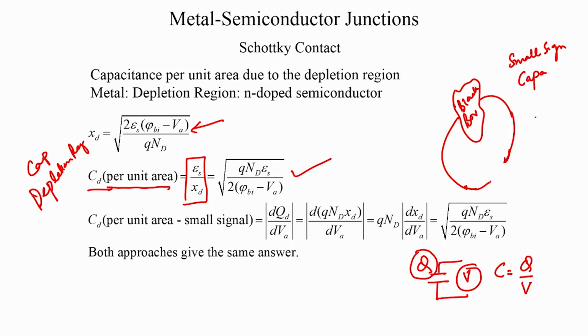Now, what we mean by small signal capacitance is this: we now apply a small fluctuating signal. We will apply a small AC signal. So, let us say it is a tiny fluctuating sine wave, if you like, at some frequency omega. So, essentially the input that we are going to give to the circuit is going to be, say, V equal to V naught sine of omega t.